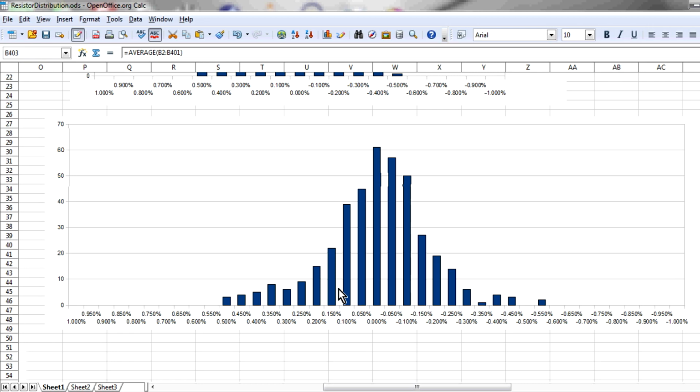Maybe they did it in the old days, but these days they would have targeted. They could target their manufacturing processes. As you tweak them, they can get better and better. And that's what Philips have clearly done here with these resistors. Their manufacturing processes and tolerances are obviously geared around a plus minus 0.5% manufacturing tolerance. So maybe they target and market them as 0.5% resistors, and they sell those as plus minus 1% because they know they're going to be well within plus minus 1%.